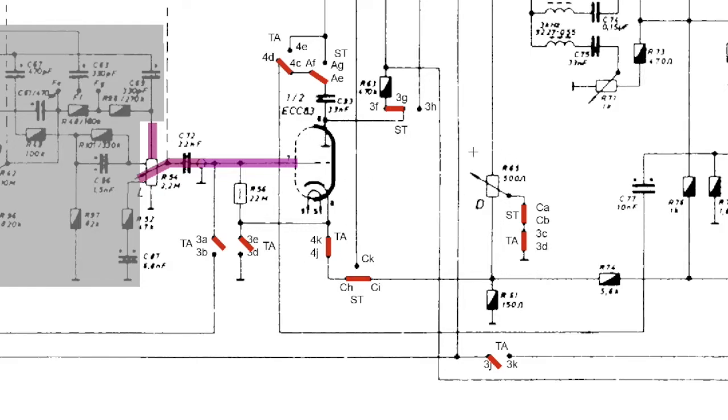There is also this potentiometer that's connected. We look at this side for now. It's connected at this point and it's connected to ground. So you can imagine if you move this wiper all the way to the left, you are shorting this point to ground. What this is doing is basically acting as the balance control. Again, not that important for now.